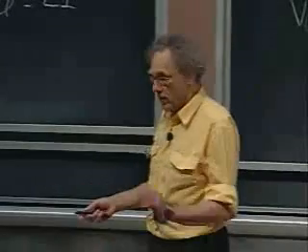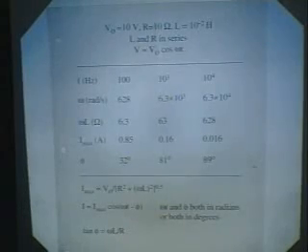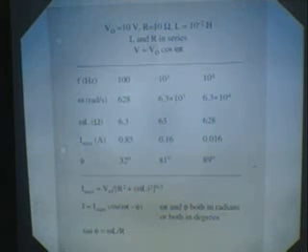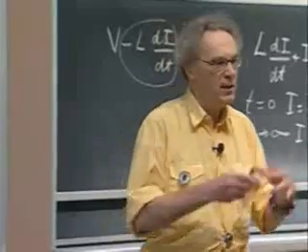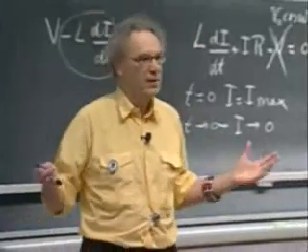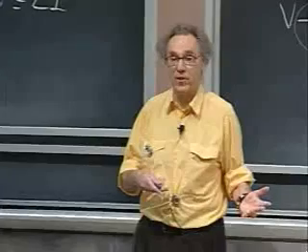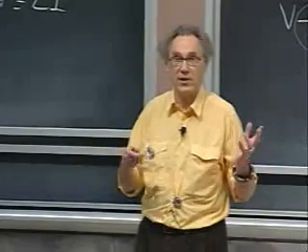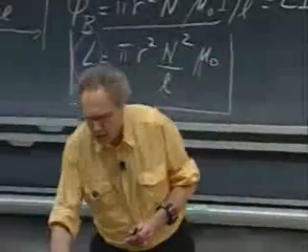And then I will turn on all of a sudden the 10 millihenry. So first I will make you listen to music whereby there is no 10 millihenry in there. And then I will turn on the 10 millihenry, and what you will hear is that the violins disappear. Because the current reduction is now huge on the high frequency, but is very little on the low frequency. And that's the idea of what a self-inductor can do for you. So if you listen to this,